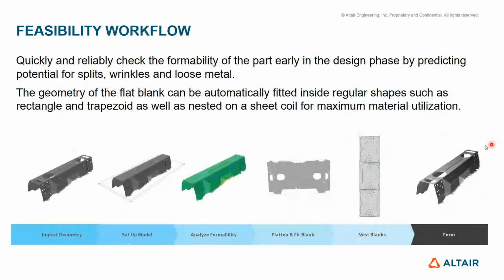So this is the procedure in Inspire Form. First you need to import the geometry, set up the model, run the analysis, formability analysis, and then flatten and fit the blank, and then finally nest the blanks.